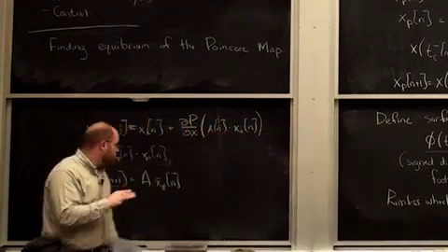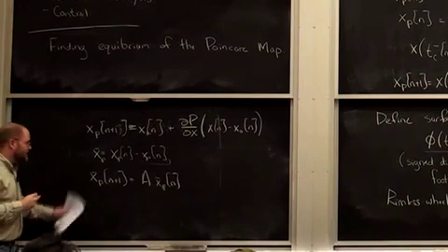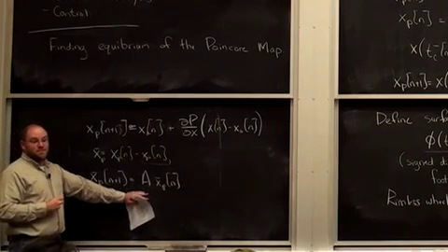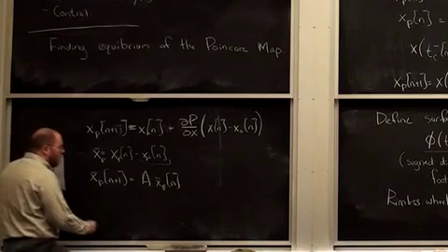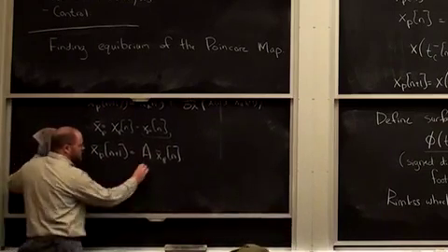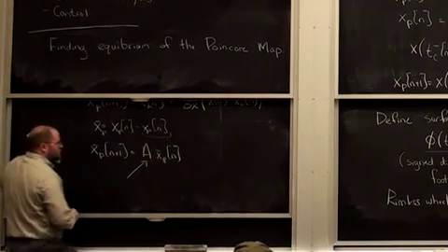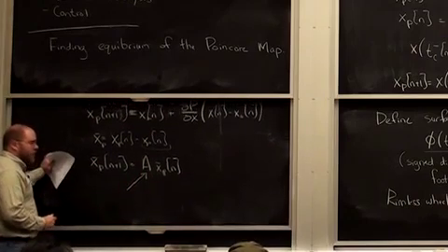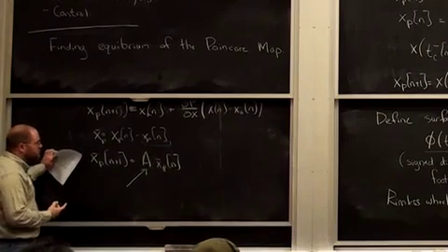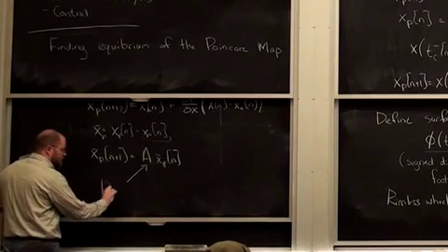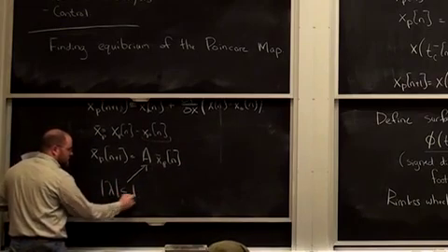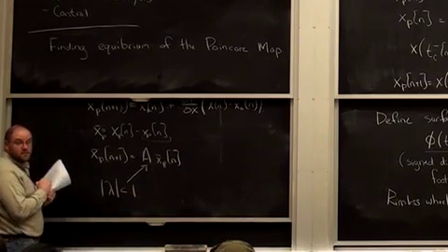There's a lot of interesting work just looking at these passive models and the stability of these passive gaits. I do want to make one note here. If you're looking at the eigenvalues of A, the way I've defined it, the trivial condition here is that the magnitude of the eigenvalues of A had better be less than 1.